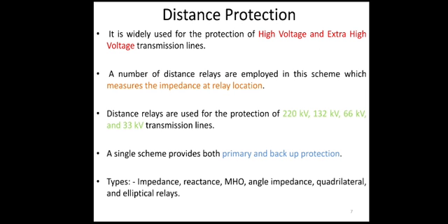The distance relays are used for the protection of 220 kilovolt transmission line, 132 kilovolt transmission line, 66 kilovolt transmission line, and 33 kilovolt transmission lines. Basically, a single scheme has the capability to provide both primary and backup protection.